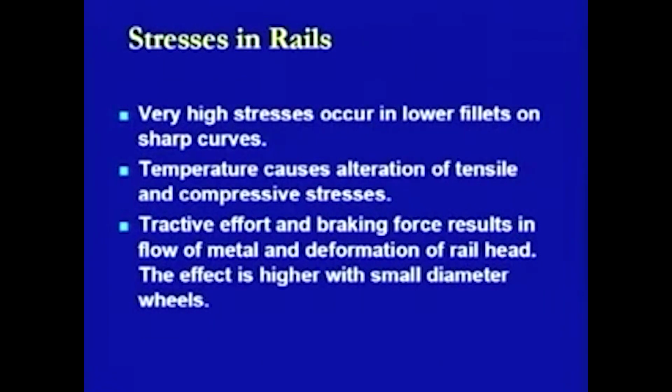The similar is the case when you are talking about the braking of the vehicle. The braking force will also result in a certain amount of stresses. Now, because of the speed and because of the interaction of the metals, as we have seen, there is a wheel which is of steel and there is a rail section which is also of steel, then as these metals come into contact with each other at a high speed and this rubbing action keeps going on, the total amount of energy getting dissipated at this point of application is very heavy.